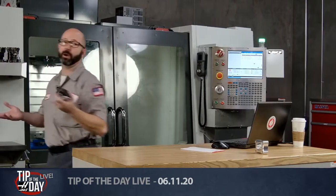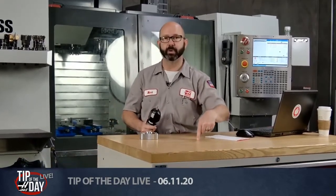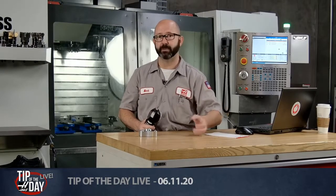We're looking at making some enhancements to the control as well. But generally speaking, we've got a video that talks about setting your tool length offsets and your work offset Z length offsets. Take a look at that. In that particular video, we show setting all of our tool offsets off a certain position. So I've set all my tool offsets here, touched them all off with a touch off tool, piece of paper, a shim, a 1, 2, 3 block.